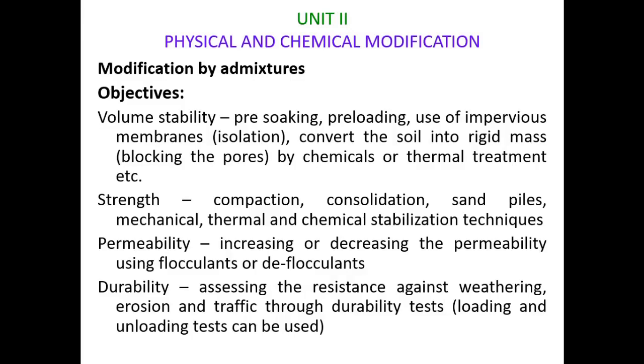stabilization, etc. The method of retarding the moisture movement using impervious membrane is effective only when there is complete isolation of stabilized soil. The chemical and thermal stabilization require sophisticated equipment and skilled labor. Hence, preloading is a good alternative for volume stability. The next property is strength.